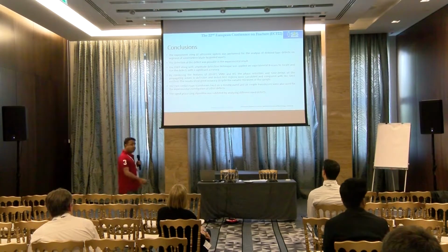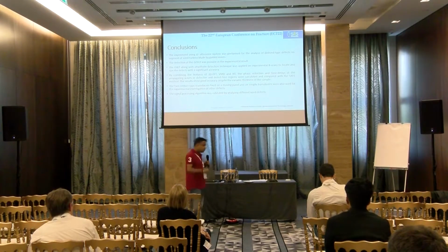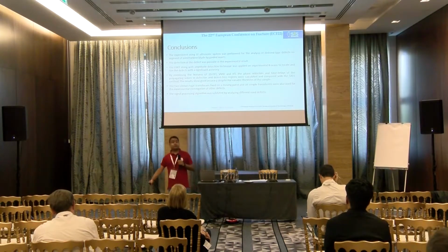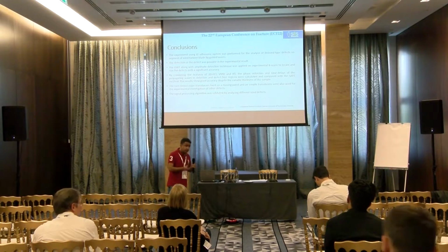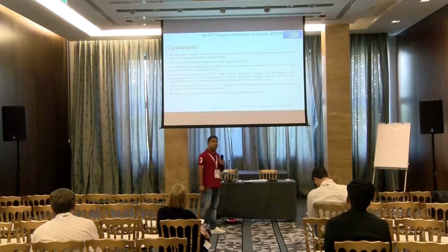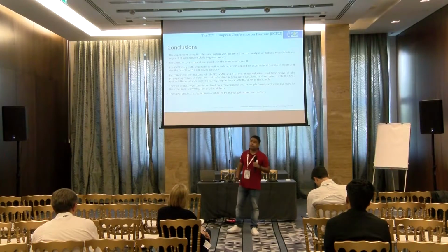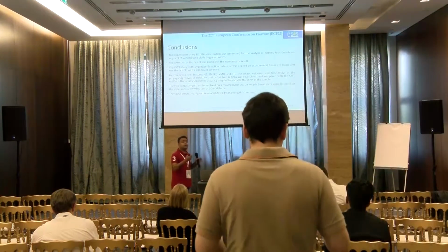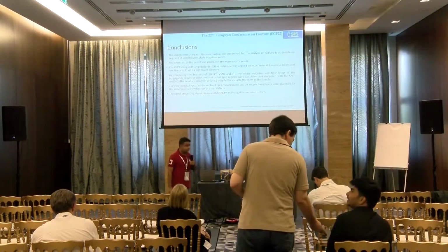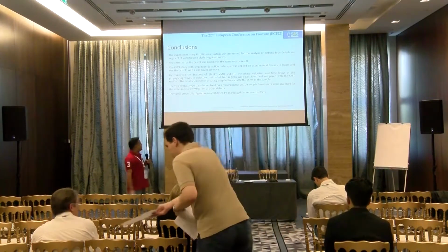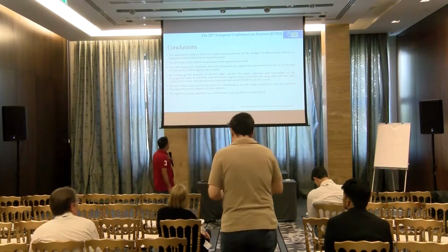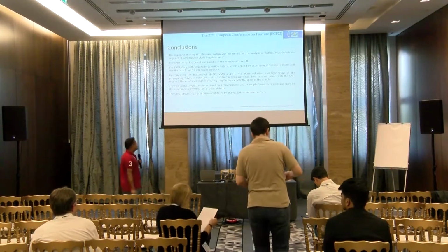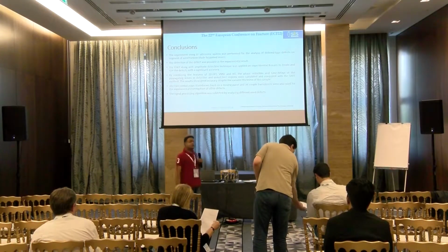So the experiment was performed using low frequency ultrasonic system in order to extract the disbond type defects on the wind turbine blade. Discrete wavelet transform with amplitude detection technique was applied to locate and size the defect. Later on, two-dimensional fast Fourier transform, variational mode decomposition, and Hilbert transform was applied to find the phase velocity and time of arrival of the ultrasound waves. The two contact type transducers and air coupled transducer was also used for the experimental investigation of other defects. And then signal processing algorithm was validated by analyzing different size defects.